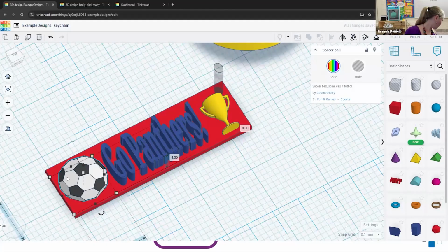Because as Evan and I were discussing lithophanes, trying to find one of my example ones somewhere here, in last month's art section, these have to be printed upright to get the detail. So there it is. You can see there's sort of a picture of a lady here. In order to print these, they have to go upright instead of flat. And so you'll just get more detail if it's upright.